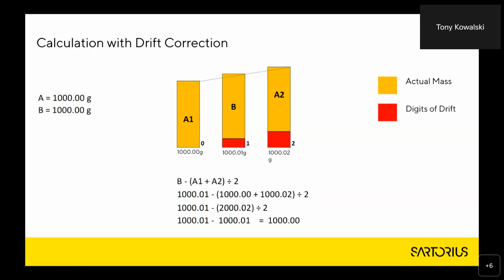So when we're calculating the repeatability in the weighing process, or if we're just testing the comparator in use, we want to just be sure that our comparator is still working correctly. In the test that we do, we could actually just use the same weight for A and B. We don't have to have 2 different value weights.